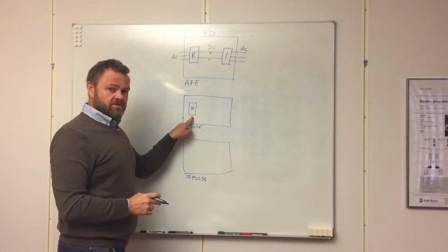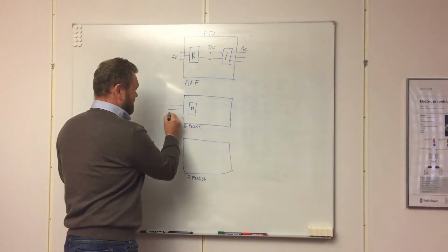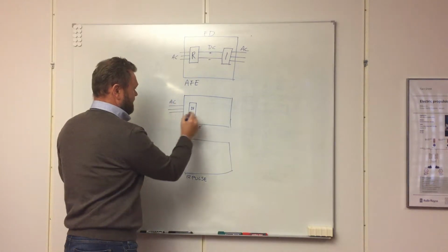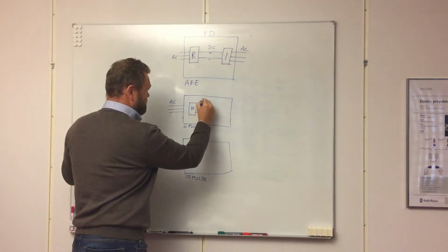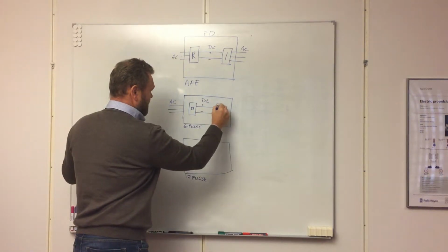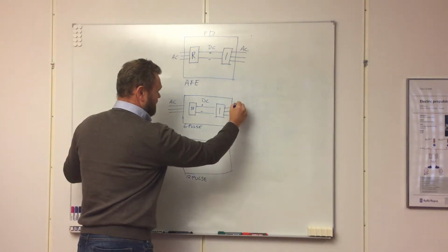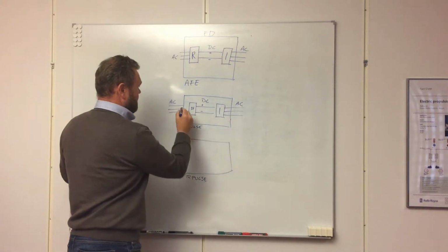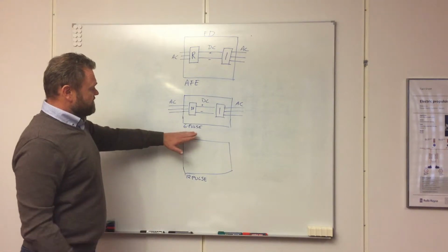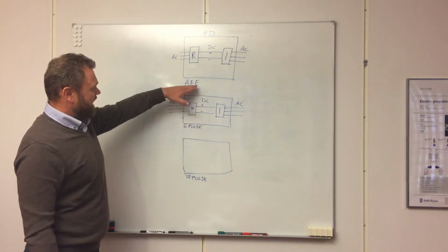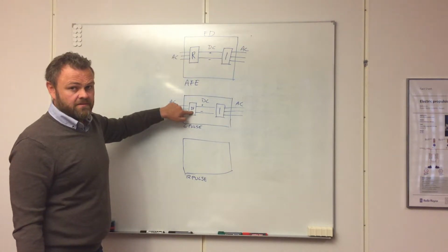The only thing these can do is rectify the 3-phase AC coming in, making plus and minus DC, and making again AC with an inverter unit. So the difference between the 6 pulse and the active front end is the rectifying unit mainly.